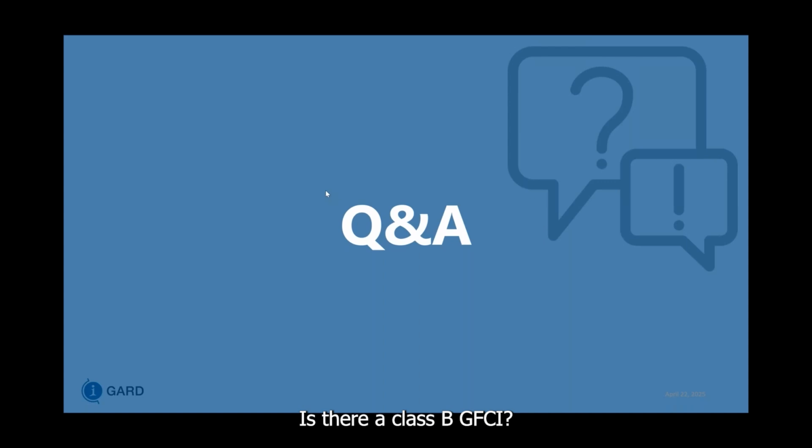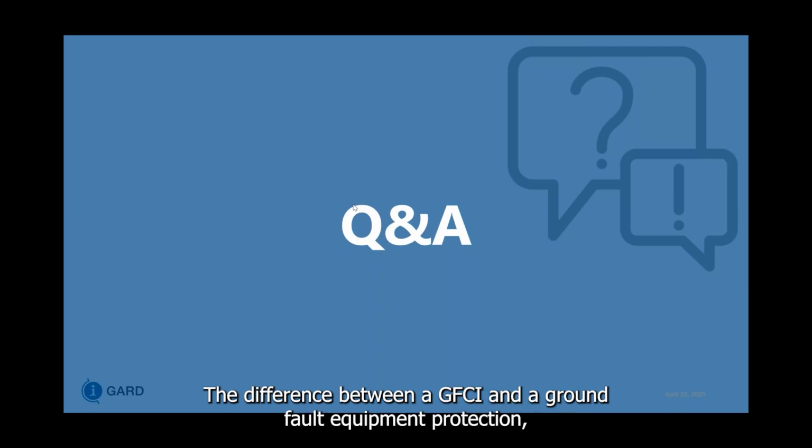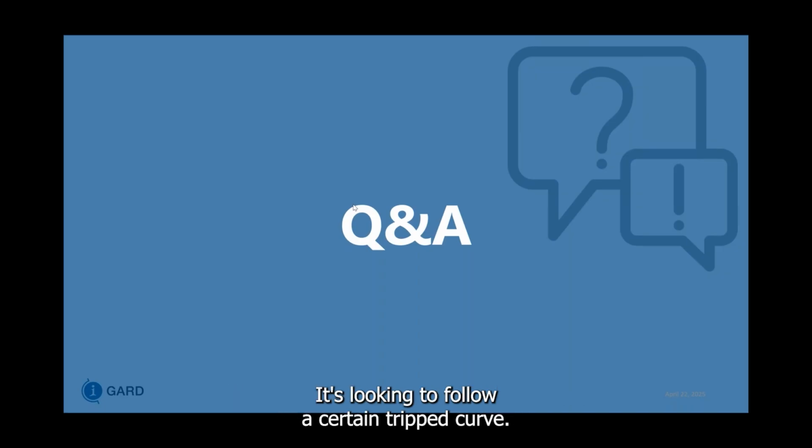Is there a Class B GFCI? There is not a Class B GFCI. They just ended up skipping right from Class A to C, D, E, as far as I know. The difference between a GFCI and ground fault equipment protection is that ground fault equipment protection is more in line with tripping, but you don't have to follow an inverse time curve, whereas the ground fault circuit interrupter is looking to follow a certain trip curve.